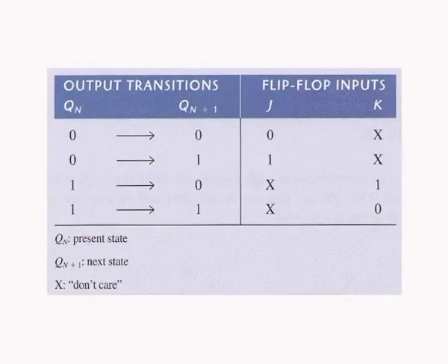In this design procedure, each cell in a Karnaugh map represents one of the present states in the counter sequence listed in the table. From the J and K states in the transition table, a 1, 0 or X is entered into each present state cell on the maps depending on the transition of the Q output for a particular flip-flop.